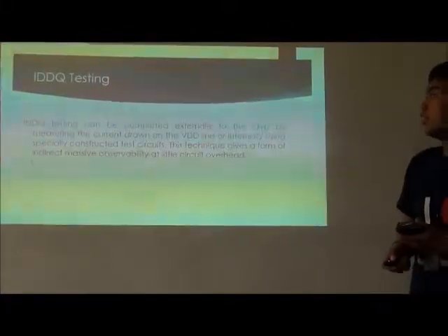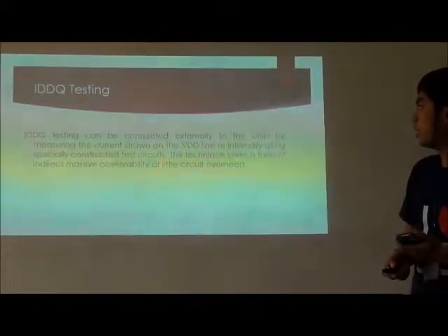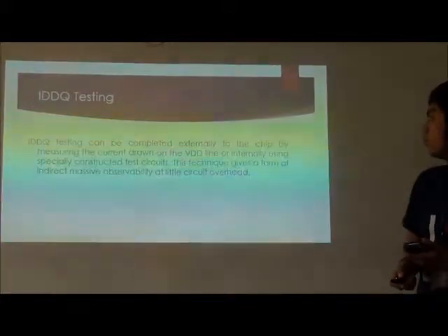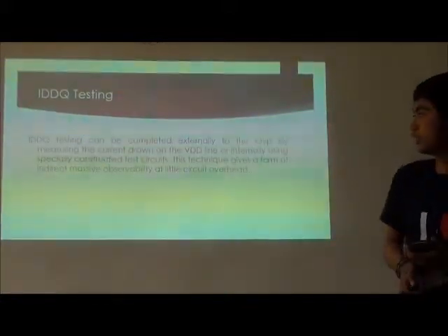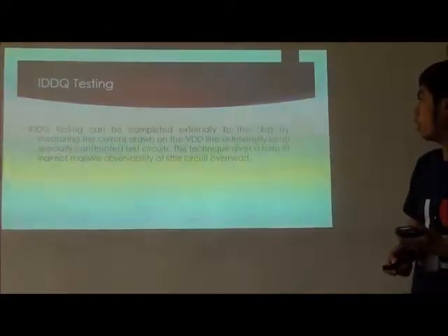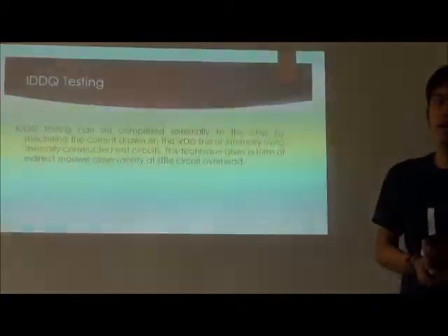IDDQ testing. IDDQ testing can be completed internal to the chip by measuring the current drawn on the VDD line, or internally using special current sensing test circuits. This technique gives a form of indirect massive observability at little circuit overhead.